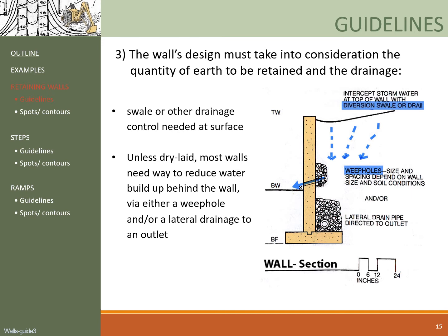Okay? Lastly, don't forget that the wall's footing extends into the soil, so a pipe above the footing that collects all water draining towards the foundation is often necessary, as shown here. Okay?